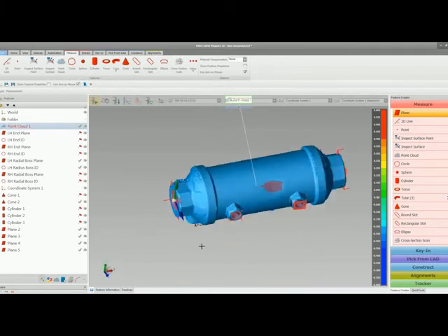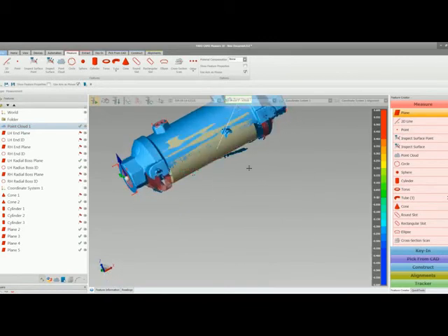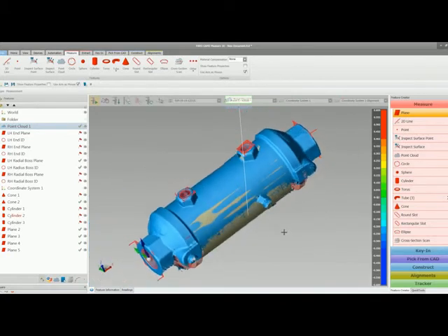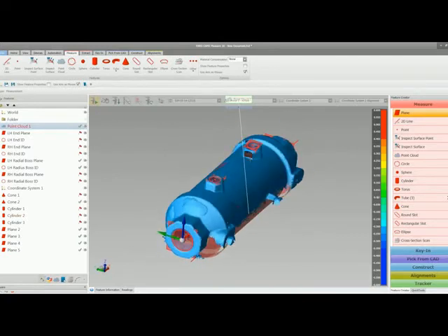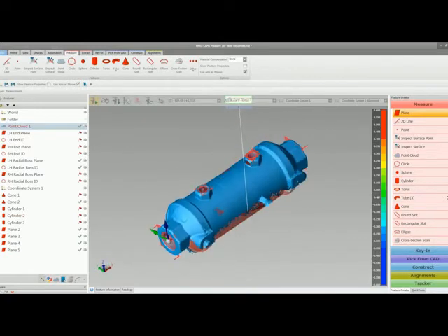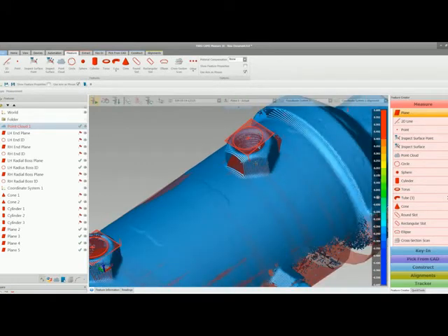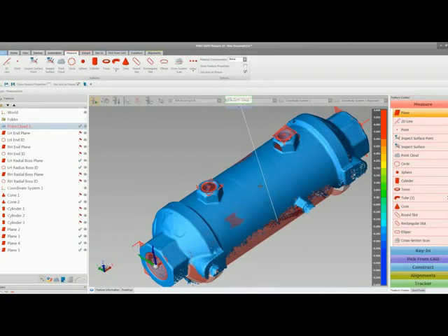So you can see how complete the image of the part looks. You just look at where there are holes in the data, and then you can just go back in and scan them if that's necessary. But like before, this is going to be reference data for me to make sure that a stock part that will assemble to this model is in the correct place, rather than actually modeling from this information.